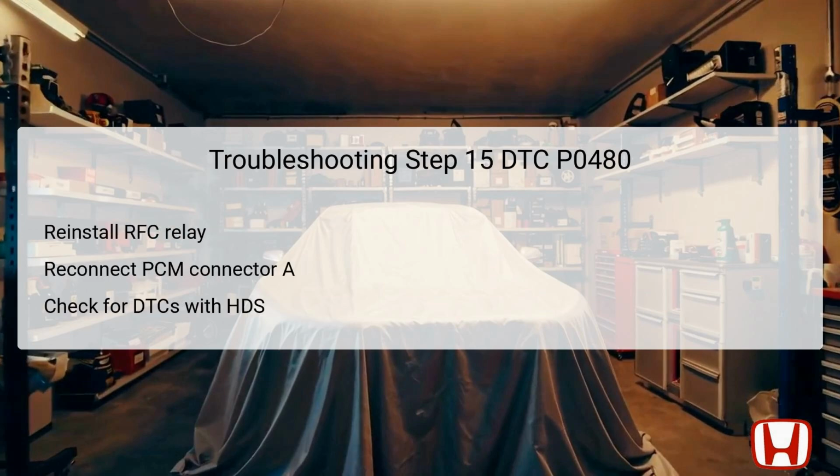Step 15 involves reinstalling the RFC relay and reconnecting the PCM connector A to restore all connections made during the diagnostic checks. The next step is to exit the SCS mode with the HDS to initiate the normal operating mode for the system. After completing this process, turn the vehicle to the on mode to prepare for checks. The ultimate goal of this step is to check for any pending or confirmed DTCs with the HDS again. If DTC P0480 still appears, it indicates ongoing issues in the RFC system, requiring further investigation into potential unknown faults.